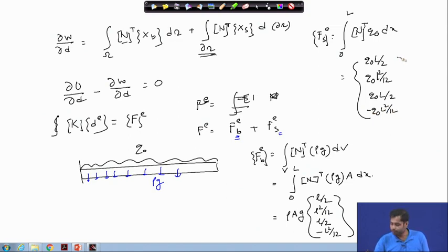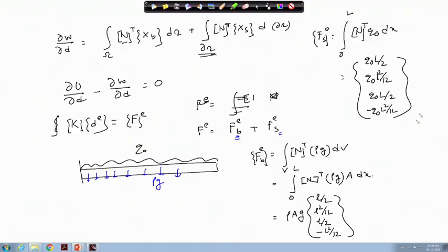Okay. Now, if you recall, in the matrix method of structural analysis, we first calculated the fixed end moments, and from the fixed end moments at every joint we satisfied the equilibrium to get the nodal load vector. And if you recall, for a uniformly distributed load, the fixed end actions were essentially this, isn't it? But here we do not have to bother about the fixed end moments and how to satisfy the equilibrium.